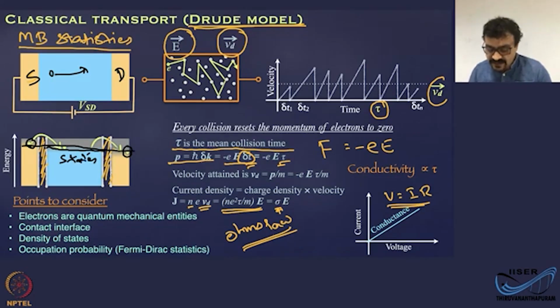Here also everything refers to states. So there should be electrons available here, there should be states available here, and there should be states available here for those electrons to traverse through. All these, plus this region in the middle, should not pose a huge resistance or non-trivial behavior for the transport. So all these things are very, very crucial for us.